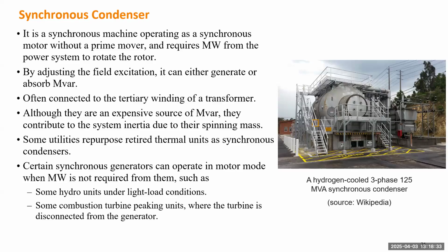So in your model, if you decide you want to add some automatic voltage controller at certain locations, but you want to verify whether those locations are good or bad, you can put a synchronous condenser there. It is basically just a synchronous generator without prime mover. The input mechanical power will be 0, and the output also 0. You still have an exciter, but you don't have a governor or turbine models.